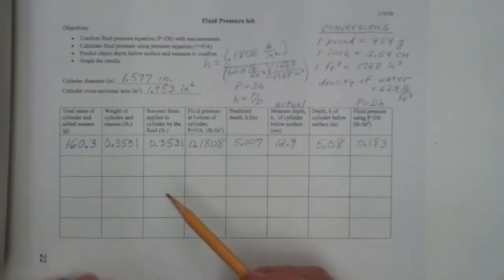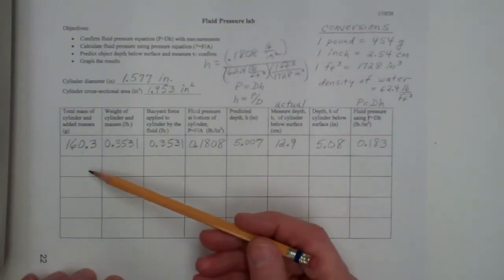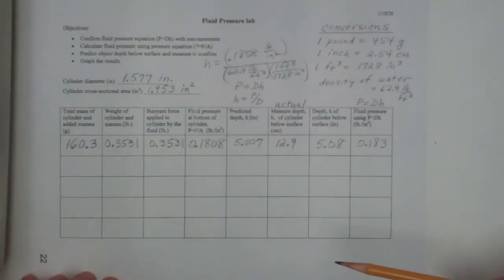And then what you'll do is the same exercise for a variety of different weights. This table just has room for 5 different weights of the floating object. Same calculations. And then the next step that we'll cover will be the graphing. There's a graph where the data can be graphed, and then you can do a calculation of the density of the fluid and see if it makes sense and reflects that we were indeed using water.